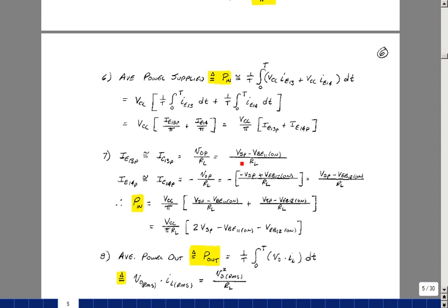And we found that the output peak was minus the input peak plus the emitter base drop of, in this case, transistor 12. So the minus signs cancel and we get basically a similar expression for the base emitter and the emitter base drop. So basically you get twice the power supply. This is really the difference of the plus 5 and the minus 5. And then subtracting off really the drops across the p-n junctions.